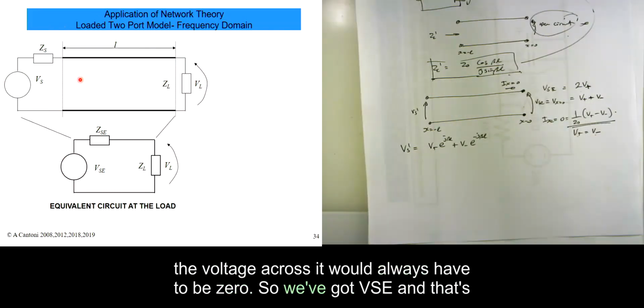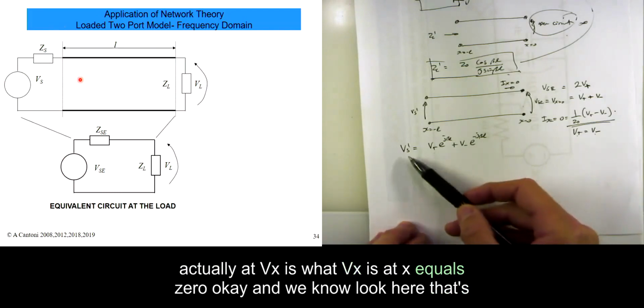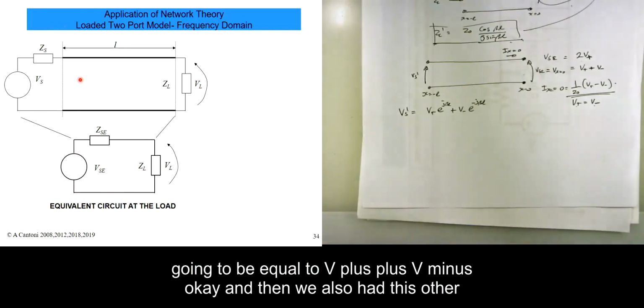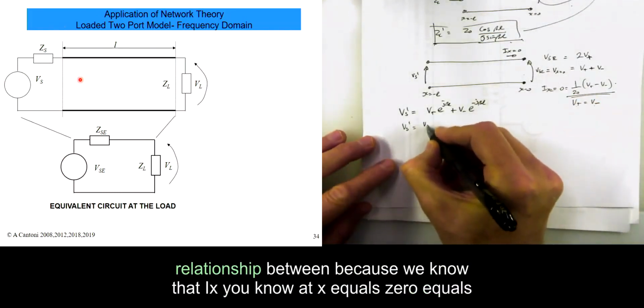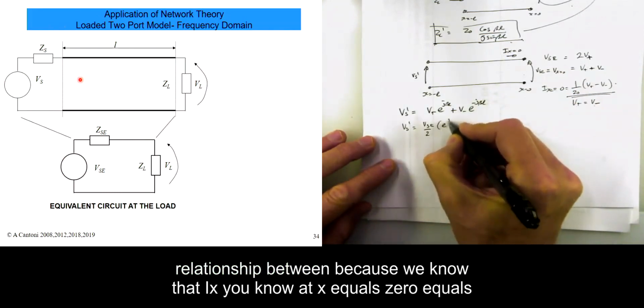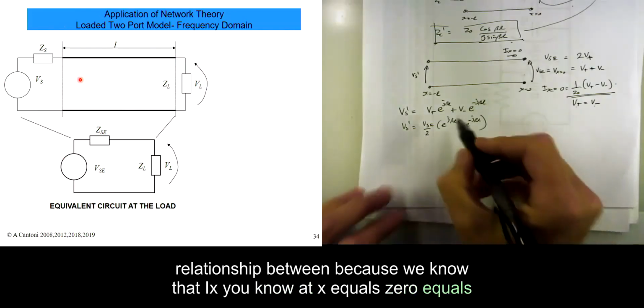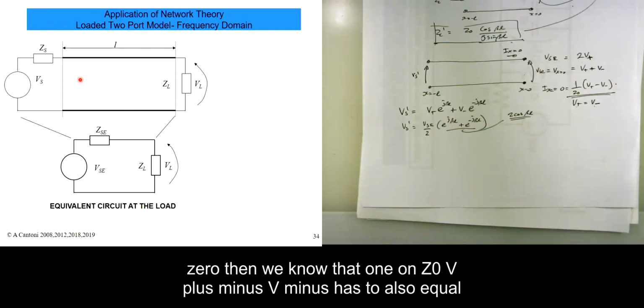So we've got VSE, and that's actually Vx at x equals 0, and that's going to be equal to V plus plus V minus. Then we also have this other relationship: because we know that Ix at x equals 0 equals 0, then 1 on Z naught times V plus minus V minus has to also equal 0.